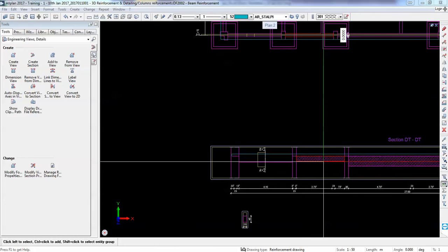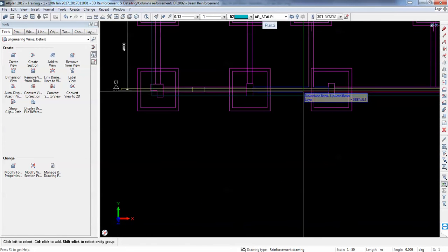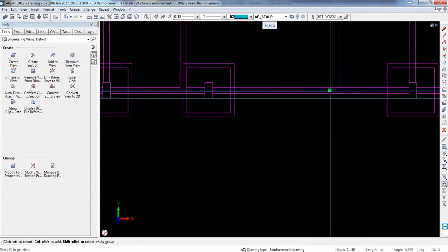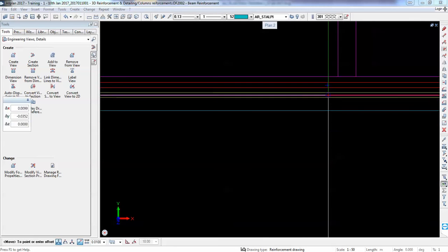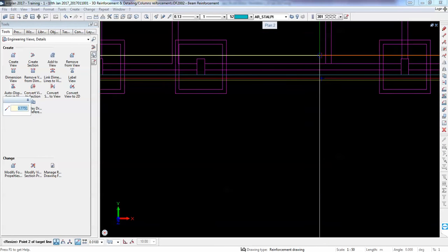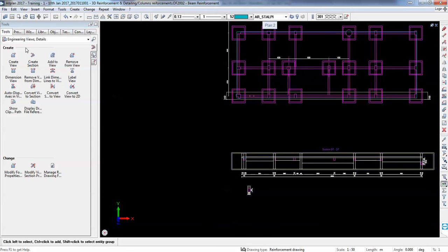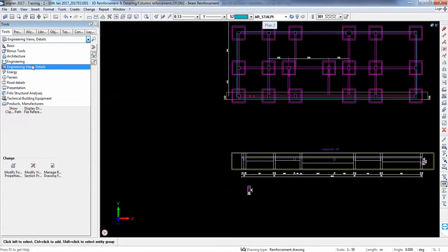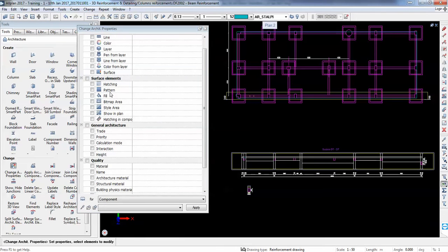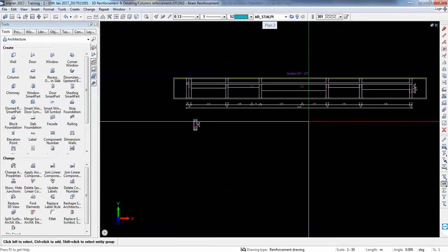Okay, let me see, but not all beams have this style area, so I will leave it as it was. So you can see this section polygon can be changed in any view and will affect it. So this is actually the depth of the view. What I'm going to do is apply this texture, this style area, to all the architectural elements made of concrete, so we'll get a good representation in our drawings, so we won't get any hatches.